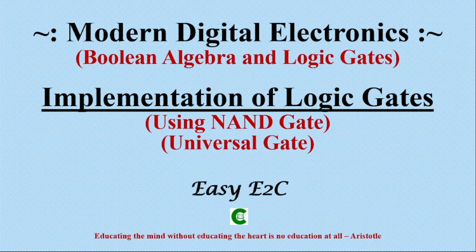Welcome to my class. By now we already have the understanding of logic gates, and we know NAND and NOR. These two logic gates are called universal logic gates because by using NAND or NOR we can implement all other logic gates. In today's class we will implement all other logic gates by using NAND gate, and in our following class we will implement all other logic gates by using NOR gate.